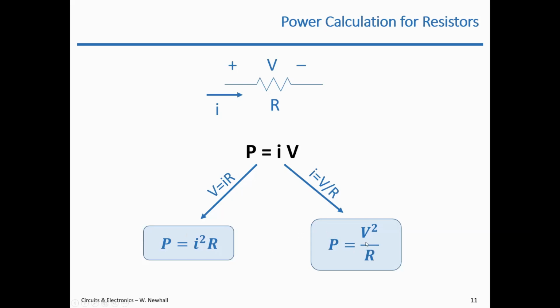Well, it's because voltage is related to resistance, right? So if I go back to this equation, if I increase R, my current goes down, right? So my current goes down. So if I increase R here, for constant current, my voltage goes up.